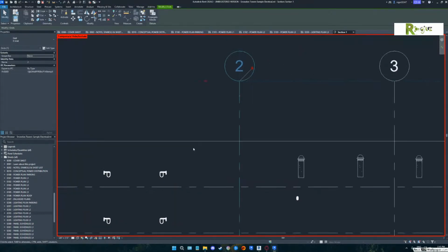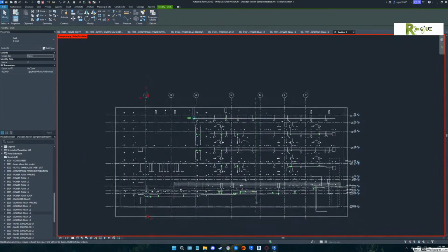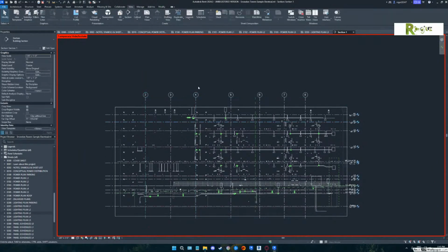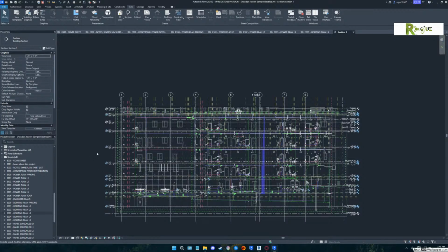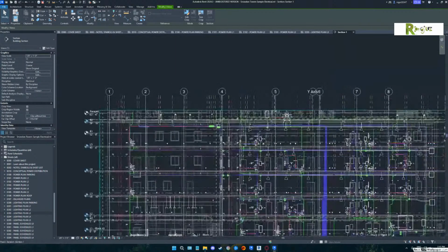So you have 5 copies of every grid on top of each other. But don't realize it because your crop boundary is so small. Okay? So turn everything back on, reset your eyeglasses. Now this time pick the crop boundary and drag the crop boundary down to L5.